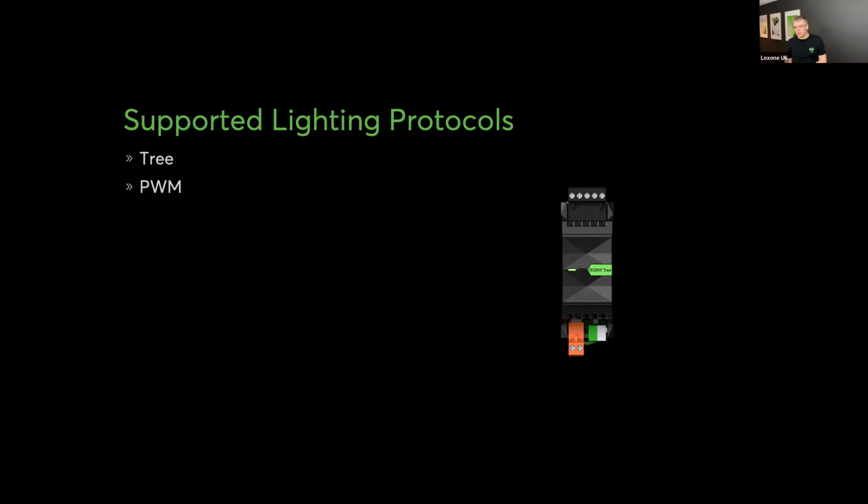Now, the RGBW dimmer, the RGBW 24 volt dimmer Tree. Now, this could be a massively longer name, because really it's not just RGBW, you can also do single channel dimming. And because PWM is just on and off, if you don't want to dim, you don't have to. If you've got an appliance, whether it's lighting, whether it's a lock, mag lock, or potentially a spring-loaded lock or a latch lock or, I don't know, strike lock, these are all running at 12 or 24 volts.